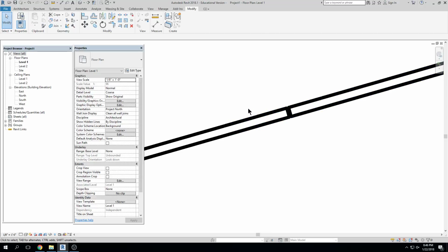Now, here's one thing, a visual setting, right? Let's talk about some visual settings. Do you notice how my line weight is reading? It's a very thick pen weight, right? These lines are all, we're in floor plan view, the lines are going to be the heaviest pen weight, of course. This is in the thin lines command, TL.